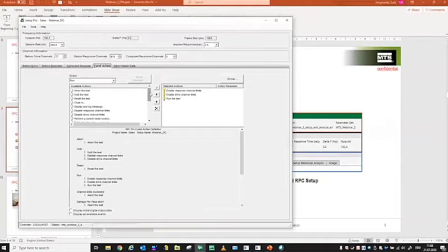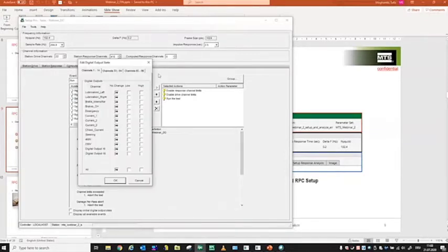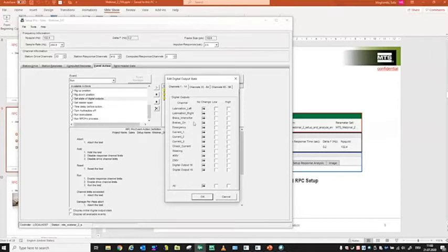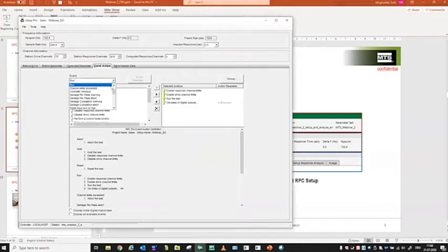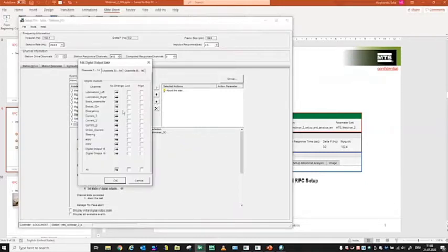So for the run sections, we are going to set, for example, here's the digital inputs and outputs, the digital outputs. For example, here the brakes, I want to have it on run while the test is running. And when it's on abort, so I'm going to switch to abort, the test should release the brakes. So what we are going to do is to set the brakes on low. I hope you are all familiar with that functionality in RPC Pro.